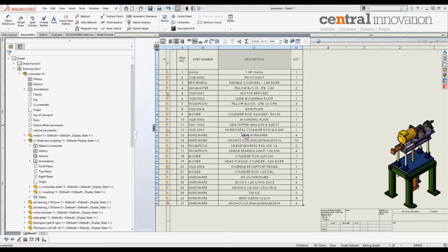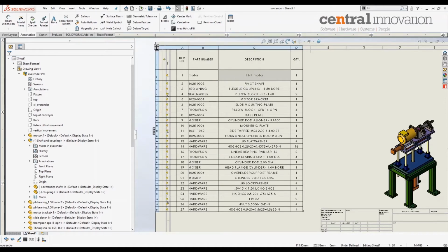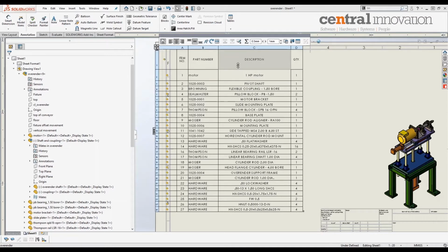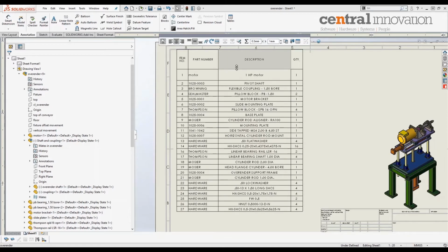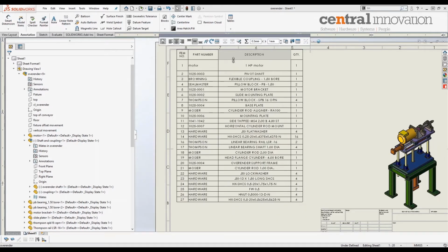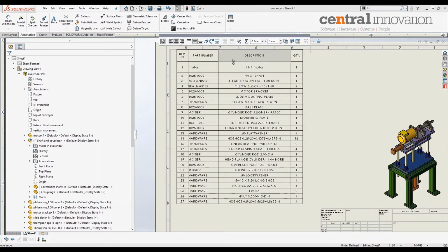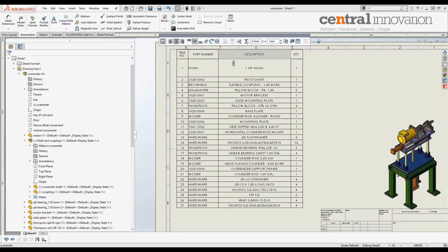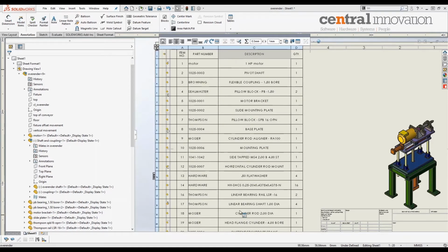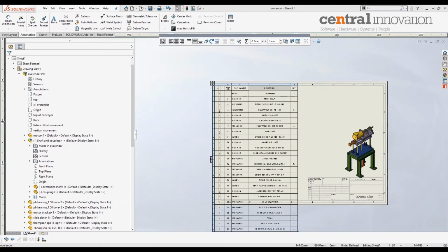But there is a little trick in bill of materials. Let's say I want all those rows at this specific height that I just specified, but I can only choose individual heights. So what I can do is click and hold the row that I want to move, and then move it to a specific point, and then press and hold the Shift key. Here's the trick.